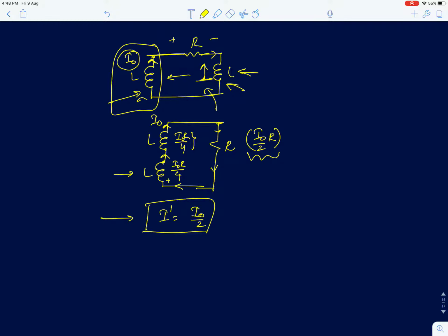Okay, so there will be a drop across the resistor, but the only difference between the previous problem and the current problem is that there is an extra voltage drop across the resistor. What I am trying to say is that the voltage in the resistor is not going to contribute to any sudden changes in the inductor current because it's a finite voltage drop. You still have to use flux conservation to find the sudden change in the currents.